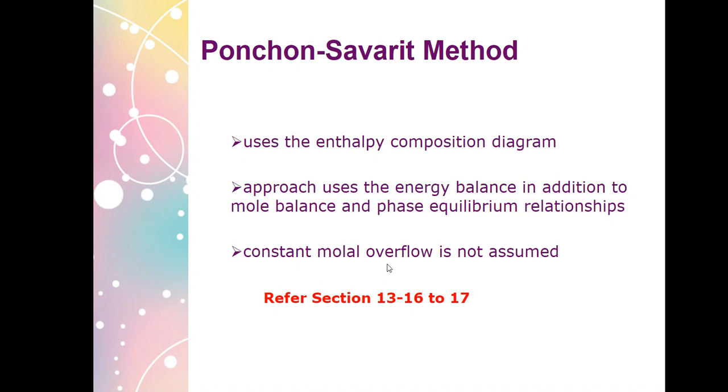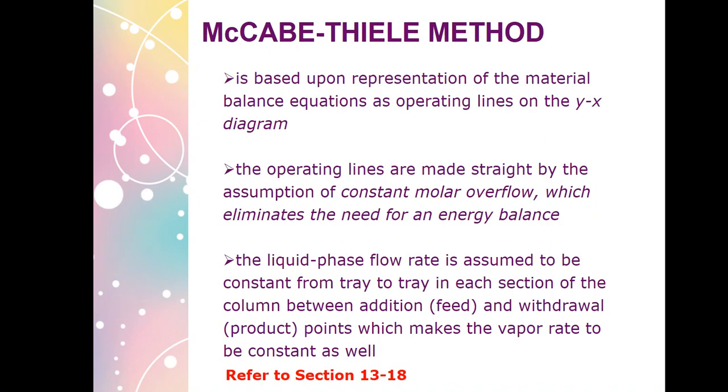So constant molal overflow, again, in this case, is not assumed. In the McCabe-Thiele method, we use this assumption of constant molal overflow. We are not allowed to use that assumption when we use Ponchon-Savarit. Anyway, it's in sections 13-16 and 13-17 of your handbook, just in case you want to complement what is being discussed here. Now, the McCabe-Thiele method is based upon representation of the material balance equations as operating lines that I have mentioned a while ago.